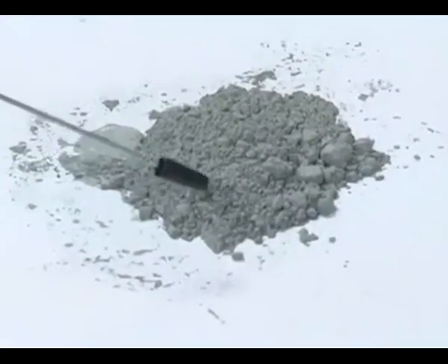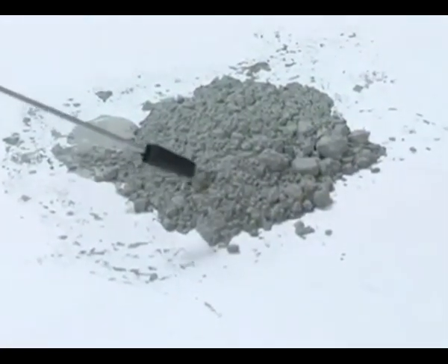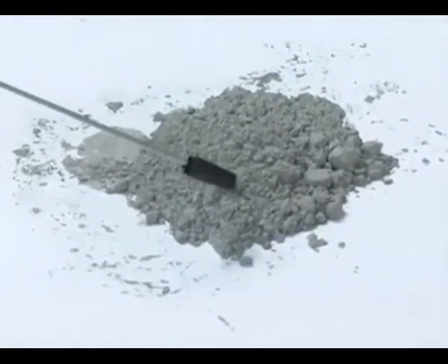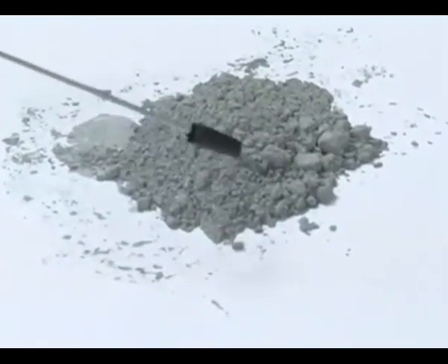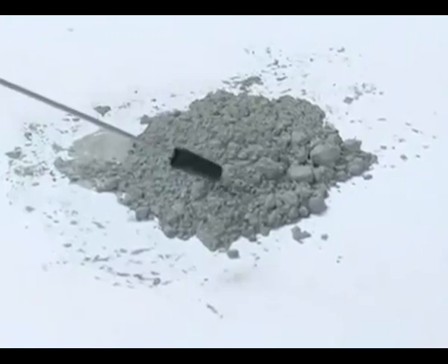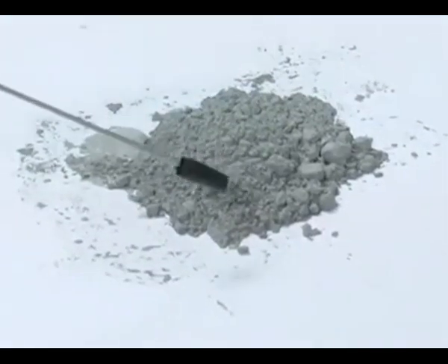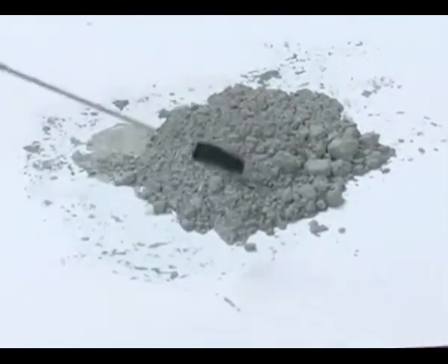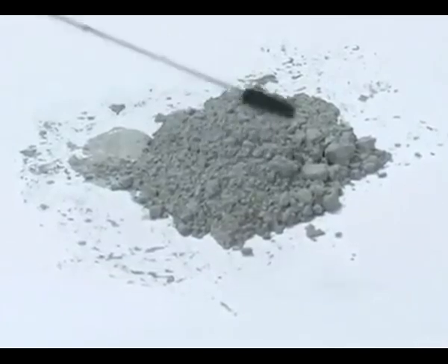The other element in the medium making is the abrasive particles. The abrasive particles are the main elements that try to shear the surface peaks of the workpiece with the help of polymer rheological medium as well as the plasticizers.